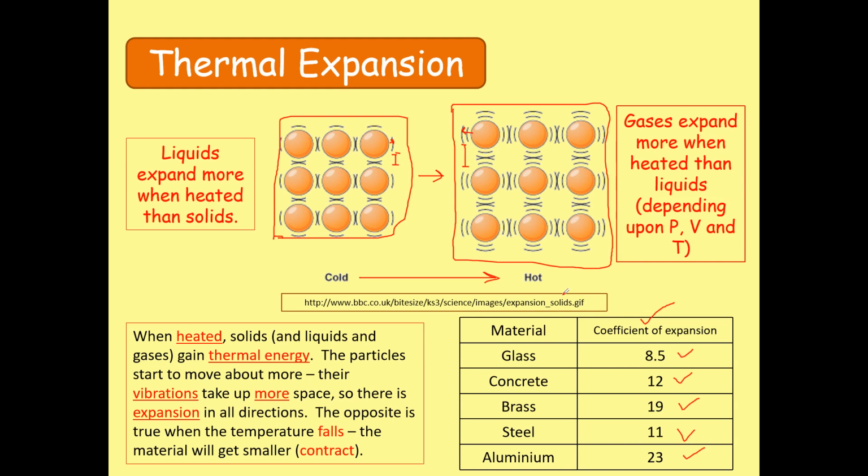Whenever we're considering this fact, we need to understand that if we're using a material for a high temperature application, we need to consider the coefficient of expansion before we consider any of these materials to be used in our design. So as a design factor, the coefficient of expansion is a really important coefficient to discuss. For example, if something is to be used at a hot temperature, then we need to account for the coefficient of expansion. We need to give some tolerance for the expansion. Otherwise, the material may collapse or get damaged if we do not allow that material to have enough space for expansion.